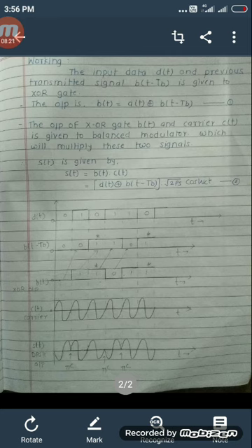Okay, so with the help of b(t) and c(t), we will draw the waveform of s(t). First of all, consider the first bit of b(t) and c(t). As b(t) is 0, that is logic 0, meaning low, the s(t) will start from negative to positive. At the end of the first bit of b(t), the second bit of b(t) will be 1. As the first bit is 0 and the second bit is 1, it changes from low to high. So there will be a phase change of our carrier by 180 degrees.